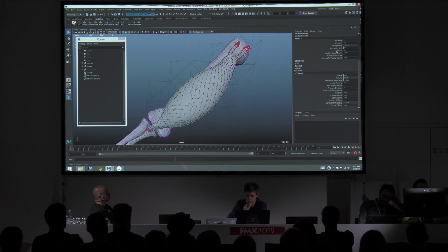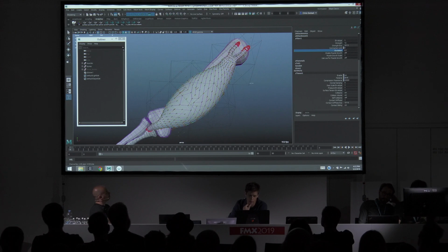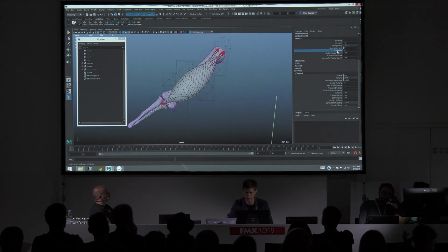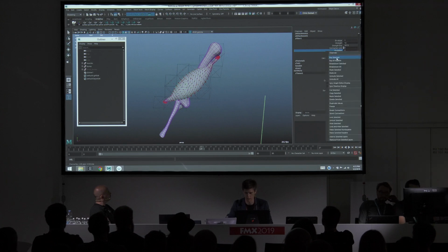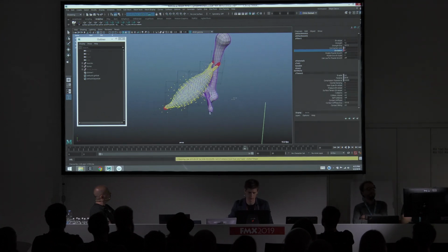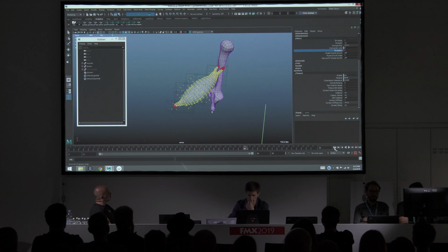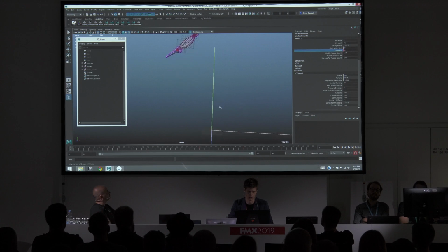There's an attribute on here called excitation, which takes a float between 0 and 1. If I scrub this, you can see that it changes color, yellow being fully contracted. This is also keyframeable. Just to show that in action, I'll go to a frame a bit further down, say here, and then add another keyframe. I'm also going to add a cache to this sim so I can scrub the timeline later.